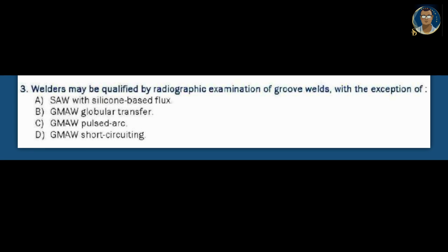Question number 3. Welders may be qualified by radiographic examination of groove welds with the exception of: number 1, SAW with silicon based flux; GMAW globular transfer; GMAW pulse arc; or GMAW short circuiting. With the exception, that means some of the processes are not allowed to use RT as an accepted NDT method. The answer is D. GMAW short circuiting cannot be tested with radiographic examination.